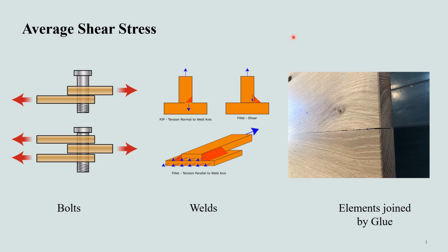Although a more precise investigation of the shear stress distribution over the section often reveals that much larger shear stresses occur in the material than those predicted by this equation, this equation is still acceptable for most engineering design and analysis. Engineering codes allow its use when considering design sizes for fasteners such as bolts and for obtaining the bonding strength of glued joints subjected to shear loadings.